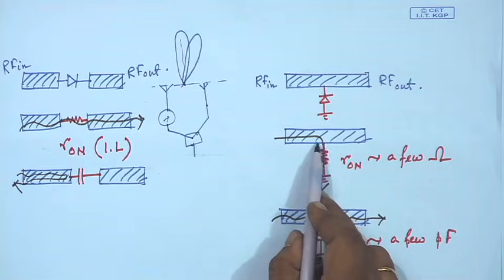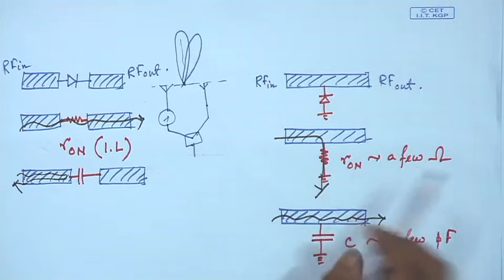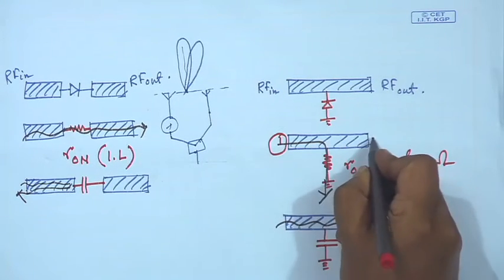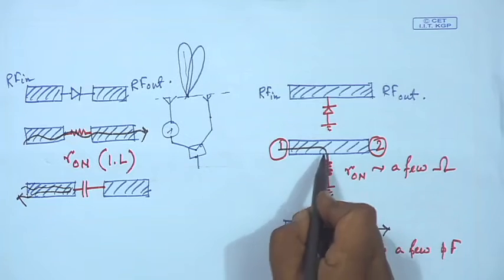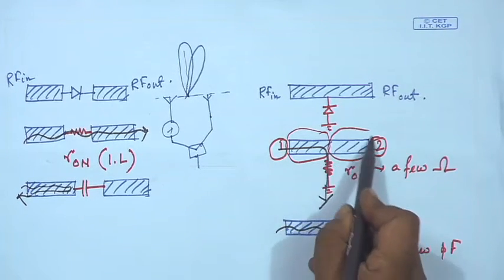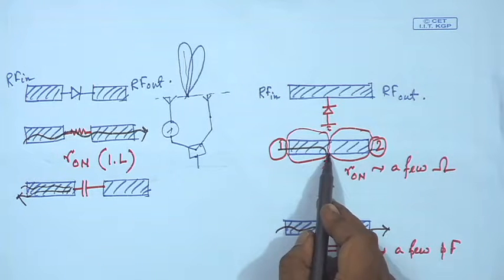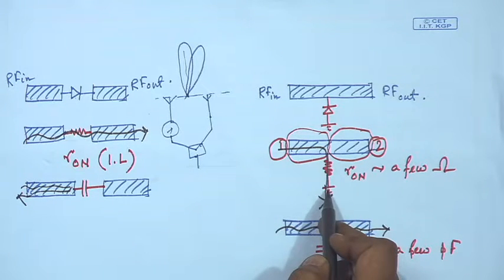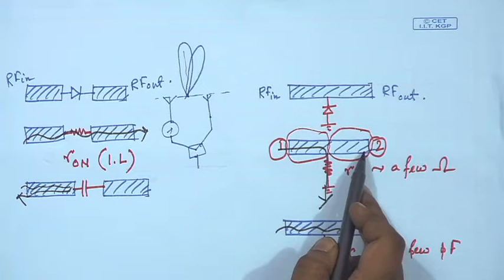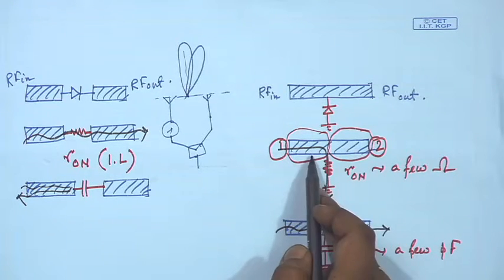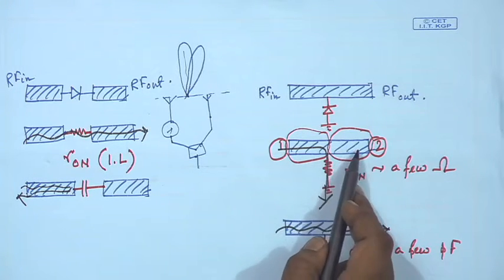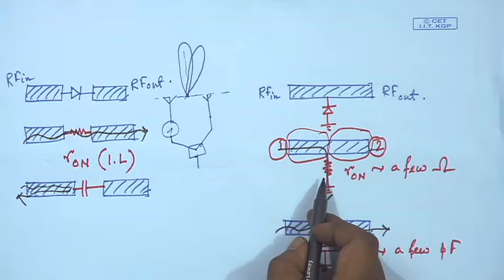we can consider it as a 2-port device, where we have port 1 here, port 2 here, and this is a section of transmission line, this is another section of transmission line, and in between we have a resistor connected to ground. So, simply by multiplication of ABCD matrices and then converting it to S parameters, we can calculate what the S11 and S21 of this arrangement are.